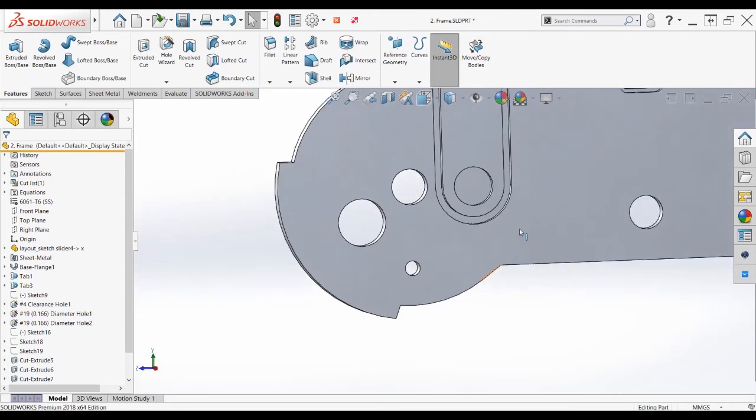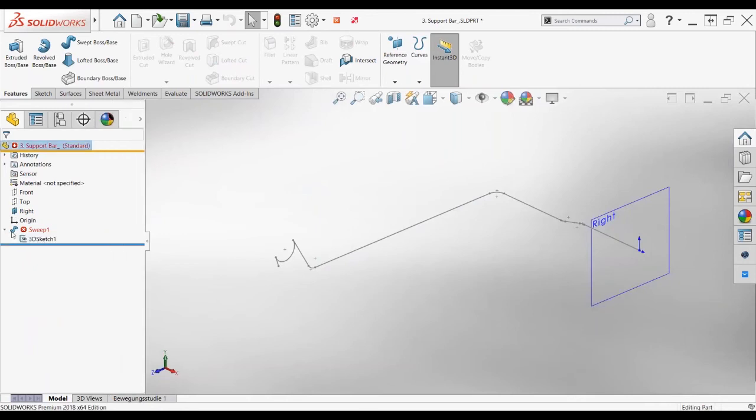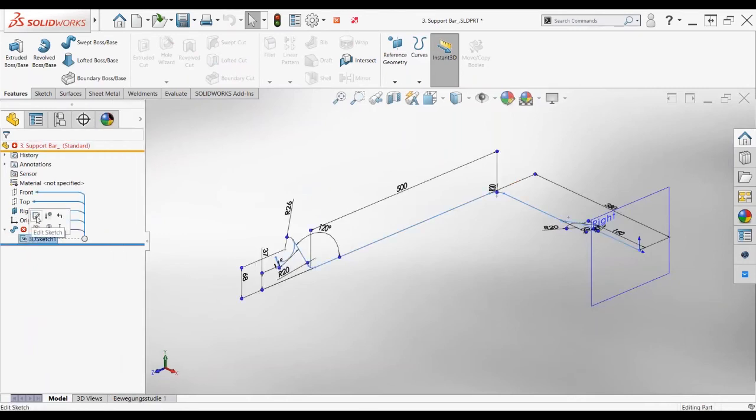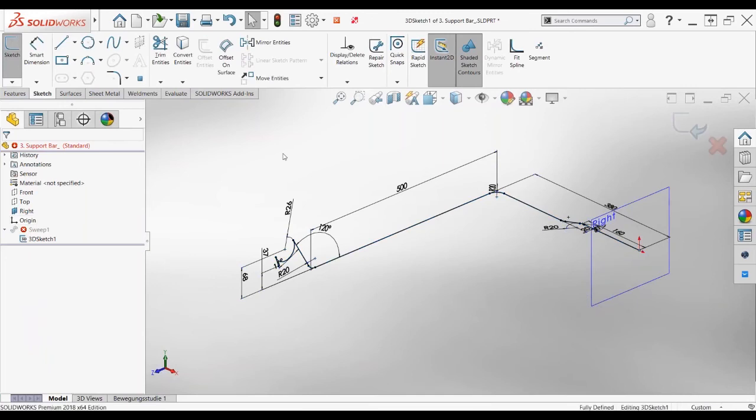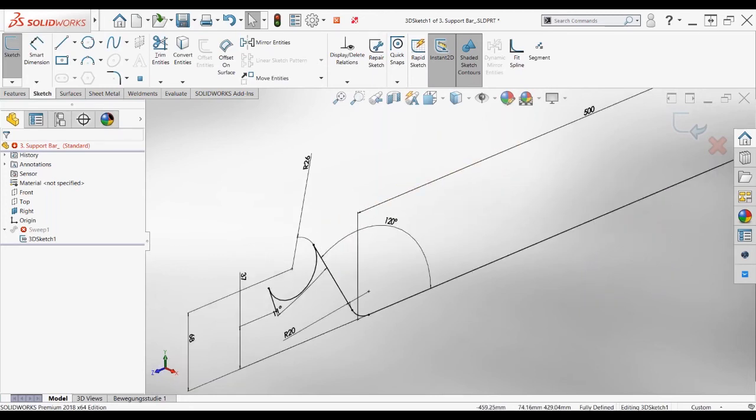All right. The next thing we're going to talk about is some enhancements to 3D sketches that happened in 2018. So this is a 3D sketch, and I have an error. My circle resolution is not set very good at all. I have it pretty low so I can maneuver really quickly because mathematically it's still a circle, but I don't need to see it as a perfect circle. The exact number, I don't know, but it's real close to the low side.